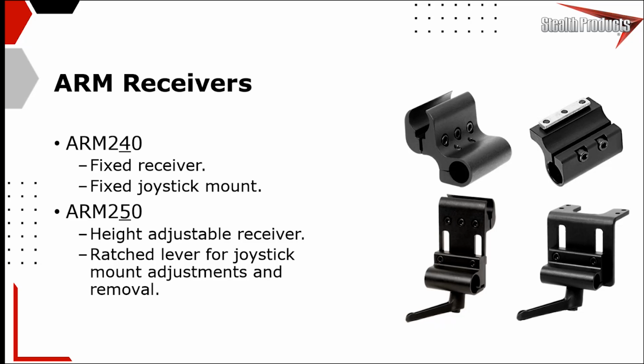It can also work on seat tracks if you do the track style mount. You can put it on a seat track very, very easily and get that joystick lower, down to the foot, things like that. The clamp style is also great for arm trough adapters when you do find a tube-based arm support. But if you'll notice the 240 style, this shorter style, it does not allow for any adjustability. So once everything's locked in place, it takes tools to move the position of that drive control. So if you use one of those to mount a Gatlin to an armrest, the Gatlin is always in that position, for example.